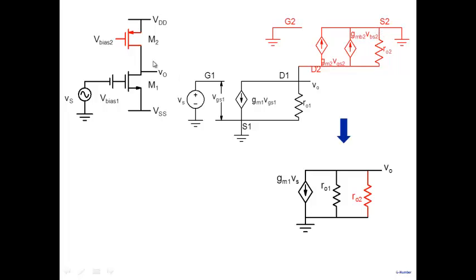Which is what I was saying, that this M2 in a small signal equivalent circuit simply acts as a resistor. It just boils down to a single resistor R02. And it's a large value of resistor, and that is what our goal was. Our goal was to replace RD here by a large resistor without occupying too much area, and this is what you end up getting. So you get a large resistor R02 due to M2 here.